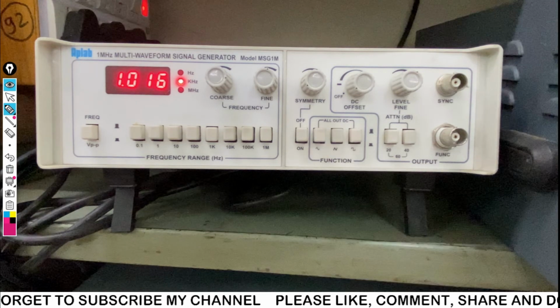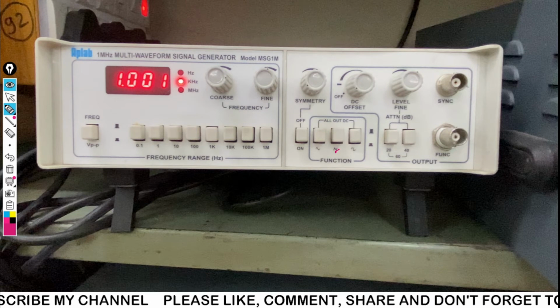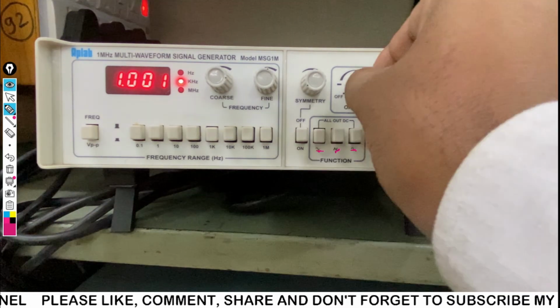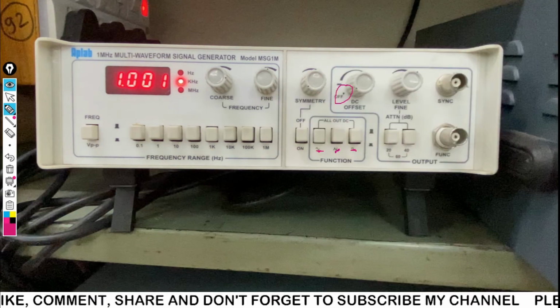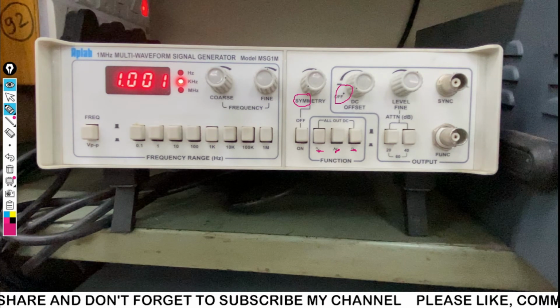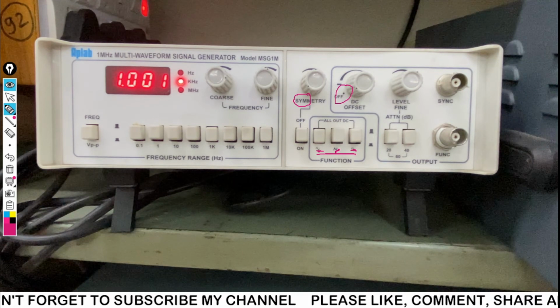Then these are the different waveforms. You can see here, if I press the triangular, it becomes a triangular waveform. If I press square, it becomes square. If I press sine, it becomes a sine. Offset is always kept at off position, and the symmetry is also at off position, at the minimum side. We don't require them while we are using these three functions with different frequencies.